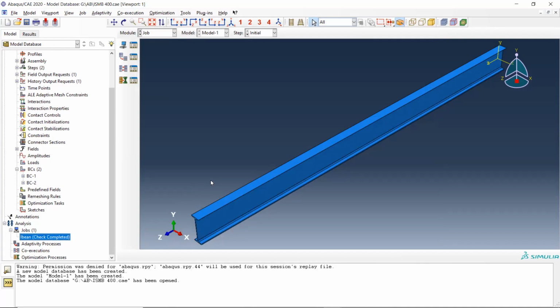You are talking about a uniaxial tensile test, right? But again, is it a tensile load or a compressive load? That's why I want to confirm. Compressive, sir, compressive load only. Okay, so one end you have to fix. So try to fix it at one end. You have fixed it. Show me the material properties first, what you have applied.